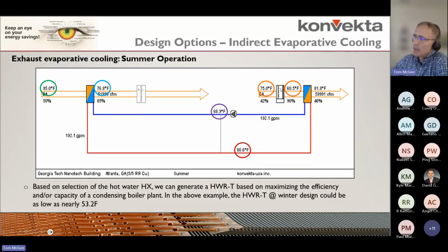and then upstream of that exhaust coil, we've got an evaporative cooling element. It can be some form of adiabatic, really any type of evaporative cooling product would work. It works really well in arid climates because you've got low humidity entering the exhaust air stream. But it can also work in humid climates if you're doing dehumidification. So this is maybe an alternative to a wrap design in those kinds of climates.